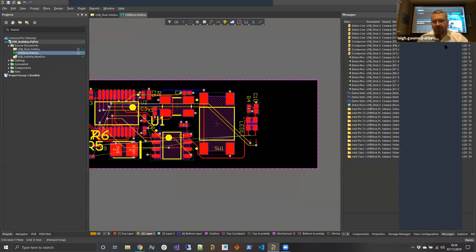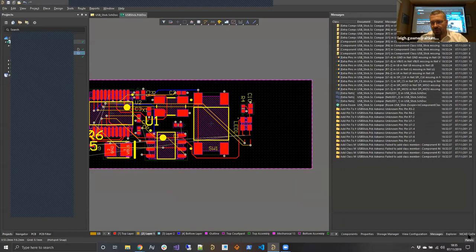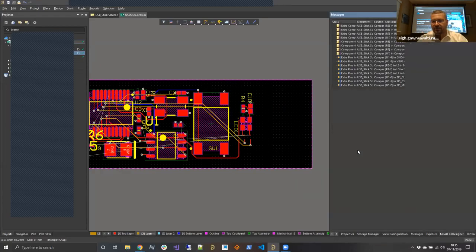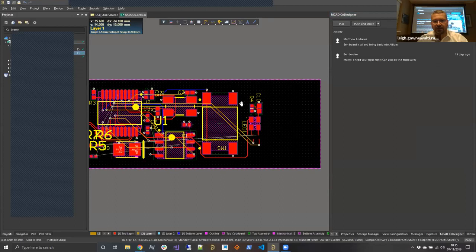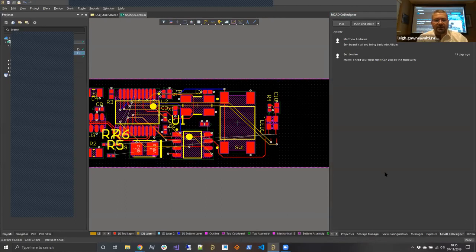Okay, right, so as a next step, I'm going to give you a quick introduction to the MCAD Co-Designer panel. What this essentially allows us to do, through Altium 365 and Concord Pro, is have a really easy way of connecting the ECAD and MCAD domains. I've got this Co-Designer panel inside Altium Designer, which is on the ECAD side of things. Then we've got plugins that sit natively in applications on the MCAD side. We support three tools today: Autodesk Inventor, PTC Creo, and Dassault SolidWorks.